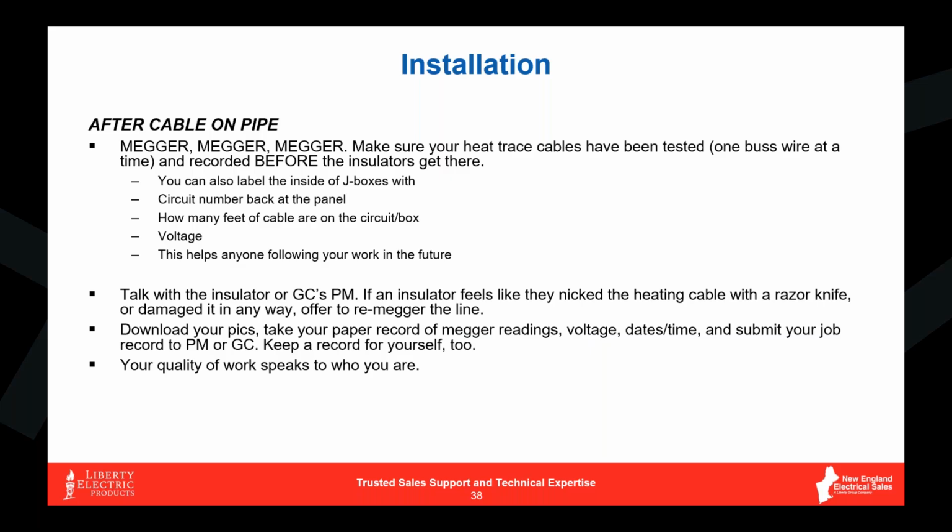All right. So yeah, if anything, communication also helps with that. Talk to your insulators, tell them that, hey, if you guys are going to be putting the insulation on over the pipe and you nick a jacket, or you think you nicked the jacket, call me. I'll just come over there, Megger, make sure everybody's good before you put all that cladding on and turn this into a really expensive redo. Okay, so just a few tips.